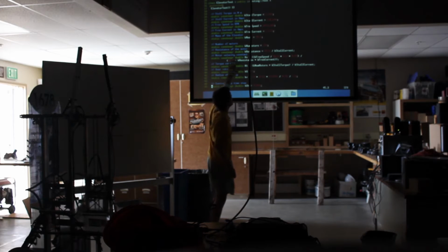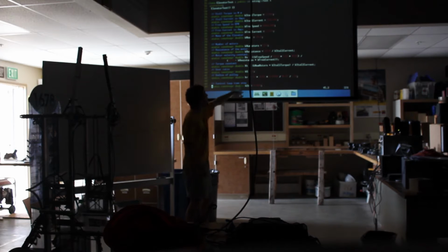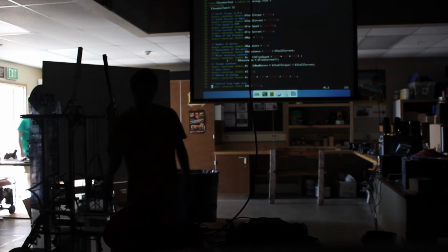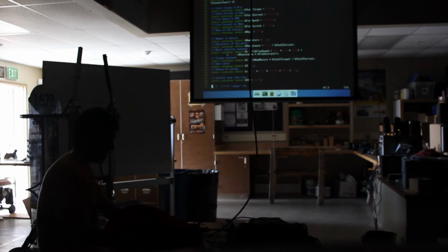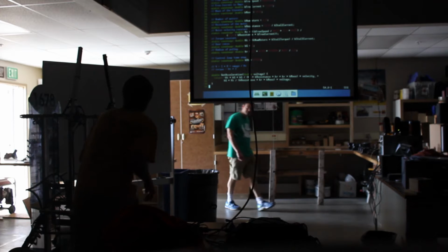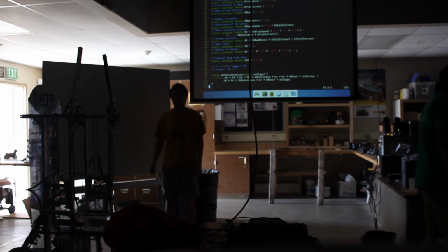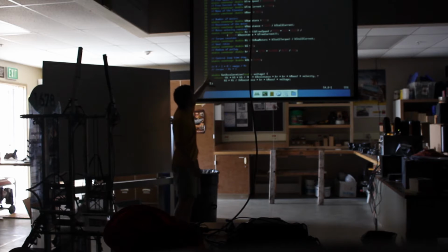We pull out, just like we did last night, our voltage constant, our torque constant, our gear ratio, and computed a pulley radius. And since I didn't erase everything, we plug that into our equation from last night up here, and we can compute an acceleration. So I typed that all up.